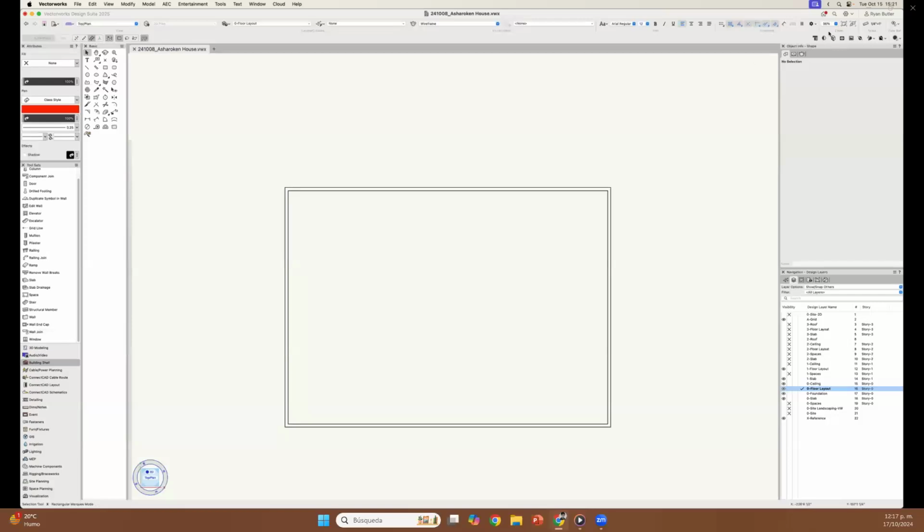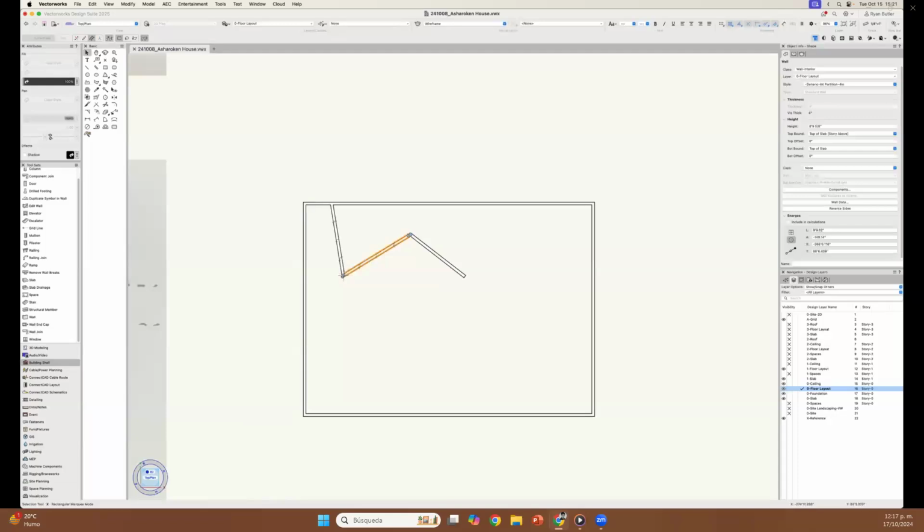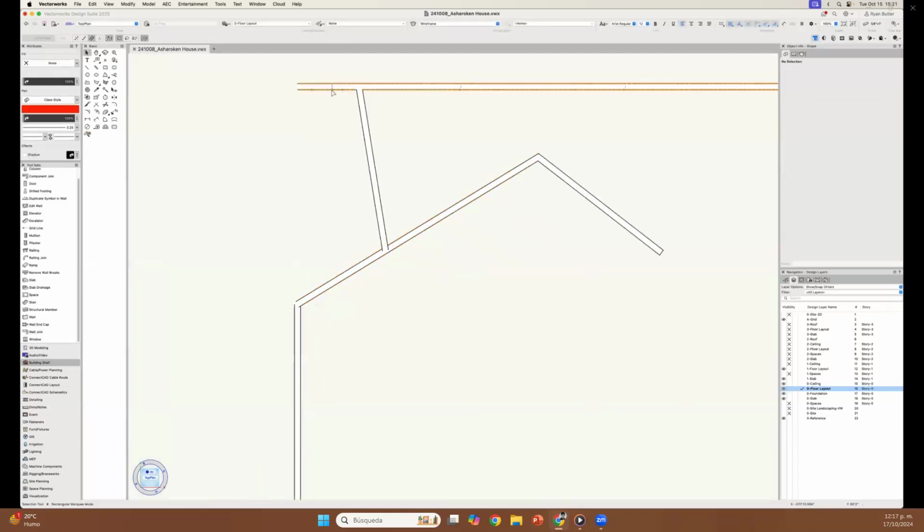Also, there's a setting over on the right-hand side. It's a quick preference where you auto join walls. If that's on, and I draw walls like this, and then I go to here, you can see that it highlights red, and then I double click, and it automatically joined that wall. Now that's the same thing if I go over here and I click and drag, it will try to join as best as it can, but sometimes you need to just invoke the wall join tool anyway.